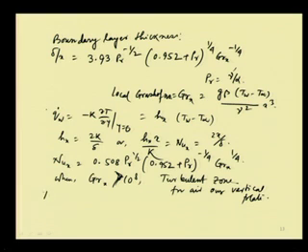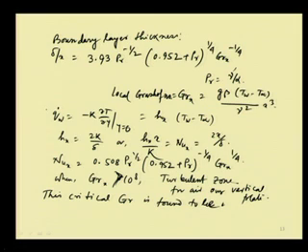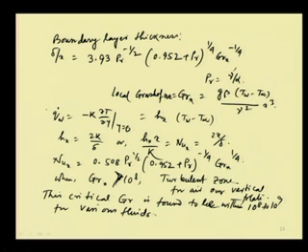So, this critical Grashof number is found to be within 10 to the power 8 to 10 to the power 9 for various fluids, and this value is used to decide whether the flow is turbulent or laminar. When it is greater than 10 to the power 8 to 10 to the power 9, then we say it is in the turbulent region. Otherwise, if it is lower than that, then we say it is in the laminar flow region.